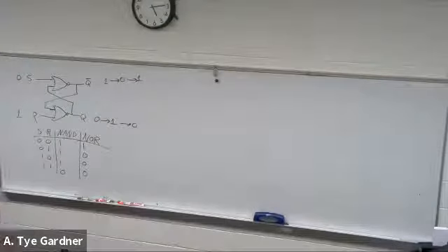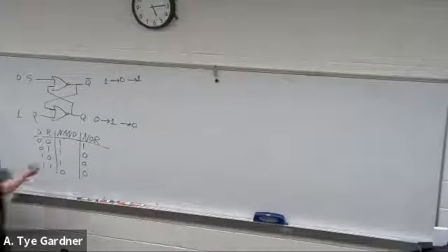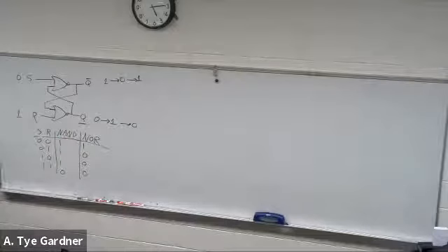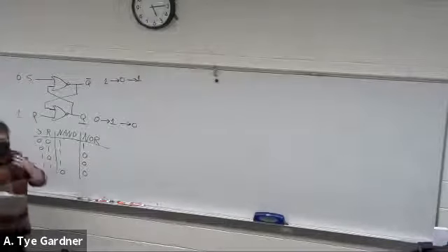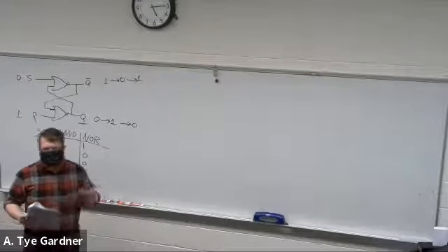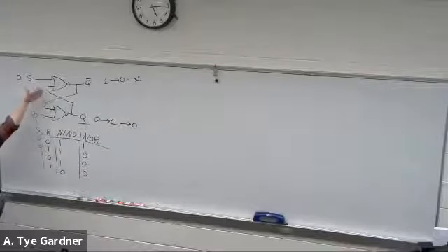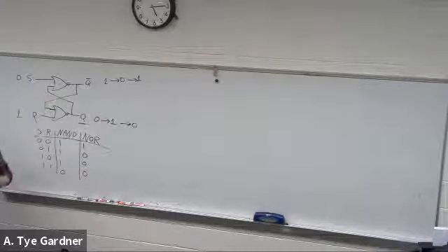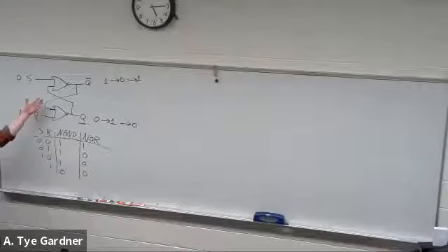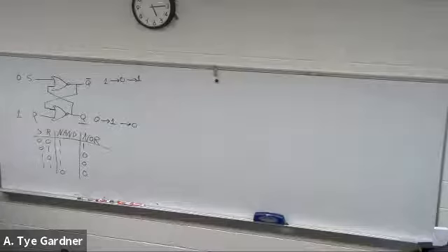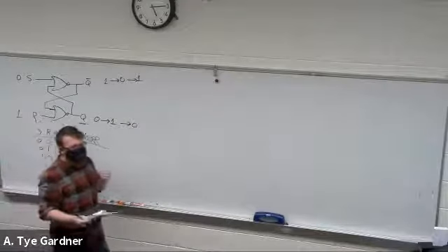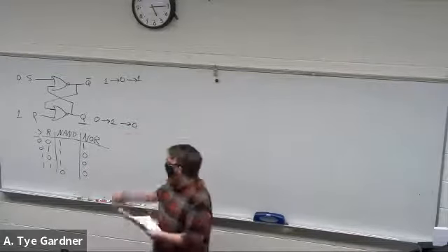That's an SR latch, set, reset. We can change what Q is. Q is what we're setting or resetting. Q bar, it just happens that we can easily access it, right? So this is part of the reason that I keep saying the inverters are nearly free. Part of that reason is because when we build something with memory, it's just as easy to have Q and Q bar as it is to just have Q, right? It's just one extra wire. It's almost free. So that's part of the reason that I say inverters are almost free in circuit costs. It's because they're just kind of there by design.